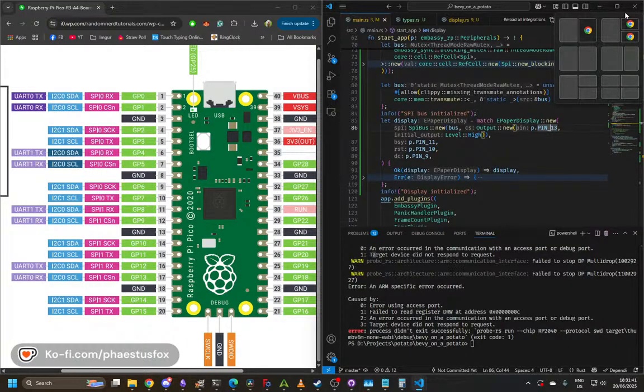So clock SCL is 14, which is 2 from the bottom. Okay. And then SDA, which is the bottom one. Okay. And then obviously ground is ground, right? So I just select that. Okay, and then VCC is 3 volts. Alright, so every pin's connected correctly, which implies what?